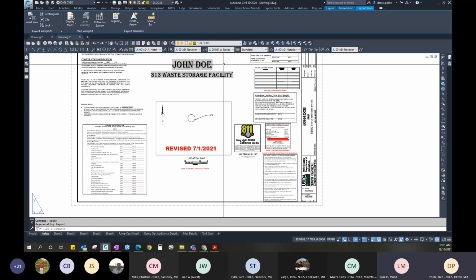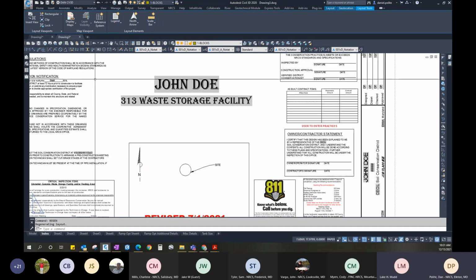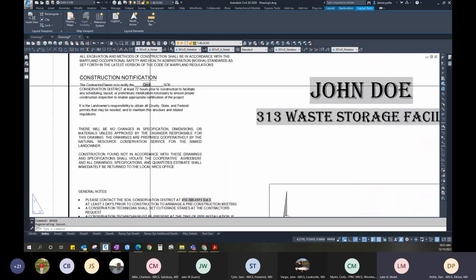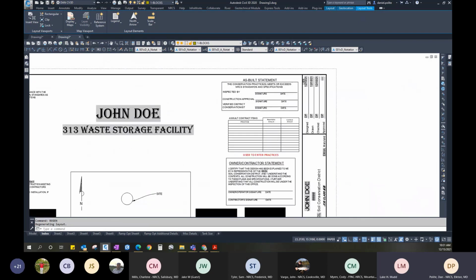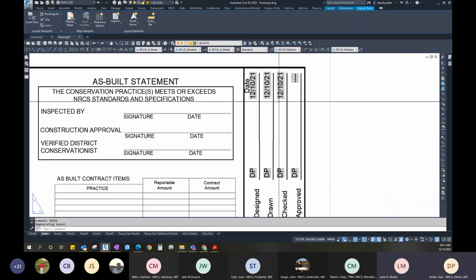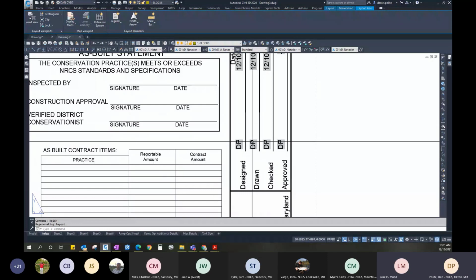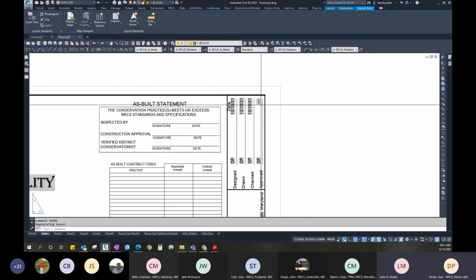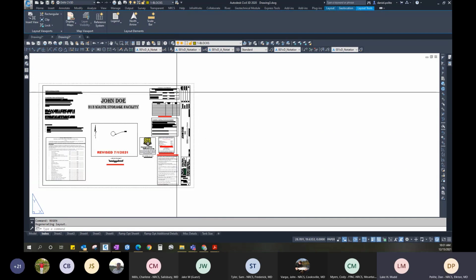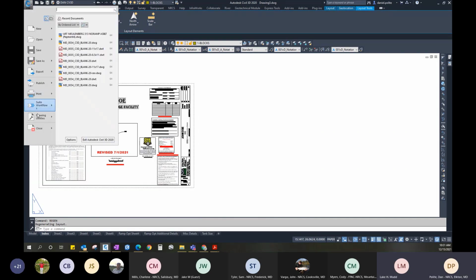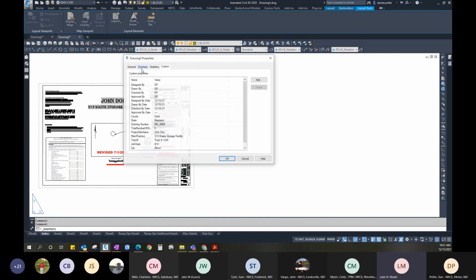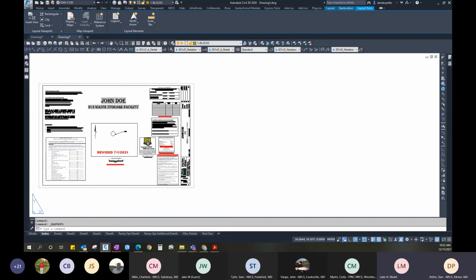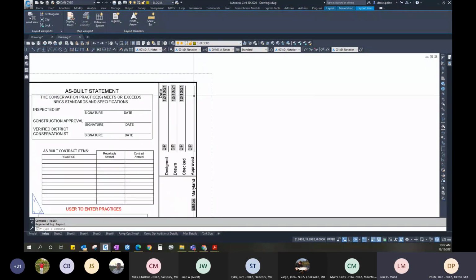And now you'll notice anything that had a name, John Doe, the county goes to Cecil, phone number, the dates, name. And again, I didn't put a space in there just for that reason. So now if I put a space in there, if I go under my drawing utilities, put a space, click OK, regen, you'll see that go away.